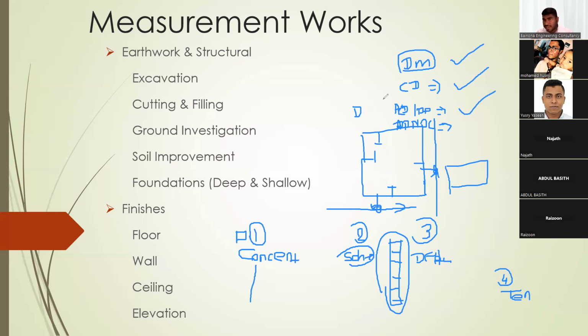Gas safety is also looked at by the civil defense, because when you are submitting to the civil defense, if the building has gas, first you have to get the approval of ADNOC, then you go to civil defense. Most of the gas lines in Abu Dhabi, you will see on the building's external elevation, yellow color pipe, because gas pipes are not allowed to come into the building. You cannot install the gas line inside the building. You have to bring it outside, because if there is a blast in the gas, it will make a problem to the building. So that is why they bring it to the outside.